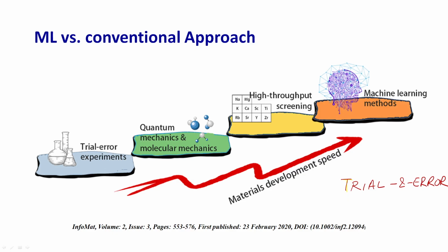Let us talk about nano indentation. In nano indentation you apply a very small load, of the order of millinewtons or even sometimes less than that, and that load is applied to an indenter, and then you indent on a material, on a particular grain or particular phase or particular boundary, and find out the mechanical properties of that. That is called nano-mechanical devices, and these devices allow us to probe the whole sample in a very fast way.